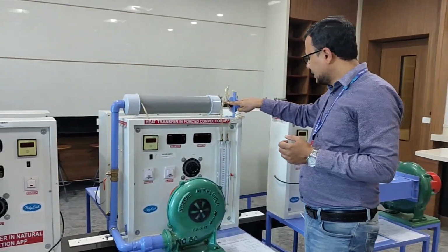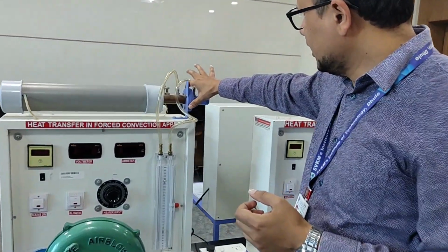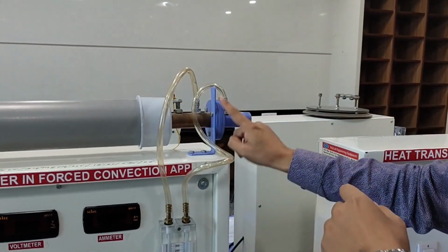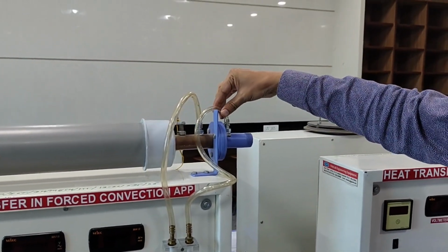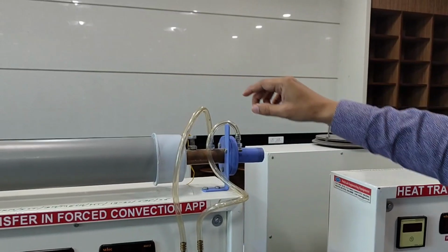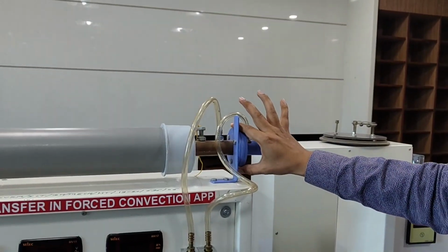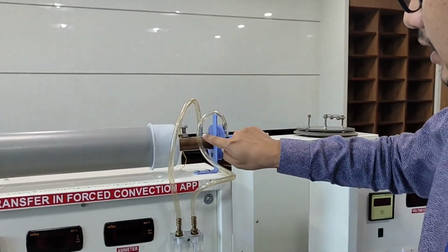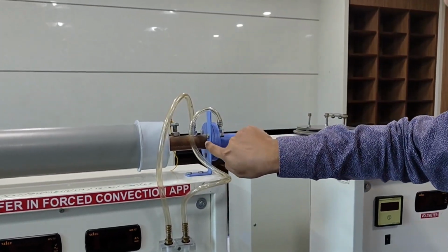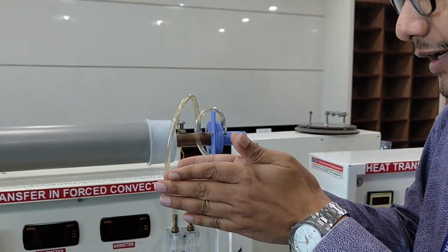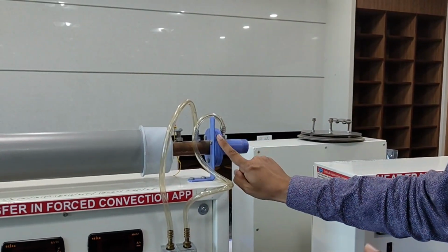Afterwards, air will keep passing through the pipe. Then it will face this orifice meter. This particular orifice meter is plugged in with these two pressure manometer limbs so that we can measure the pressure. We know the working principle of orifice meter from our second year fluid mechanics. At the inlet, the pressure will be higher. Then at the orifice meter, there will be sudden reduction in the area. Because of that, there will be reduction in the pressure.